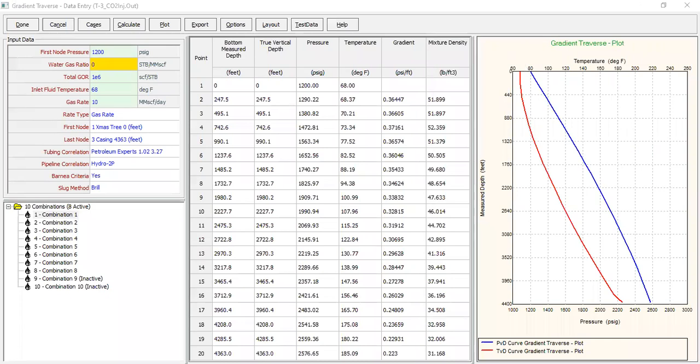Hello everyone. Now I will continue my exercise. I'm assessing a conversion of a gas producer to CO2 injector. And of course, for CO2 storage, we want to maintain CO2 to be in a liquid or supercritical, or we also call it a dense phase, along the wellbore when the CO2 is injected.